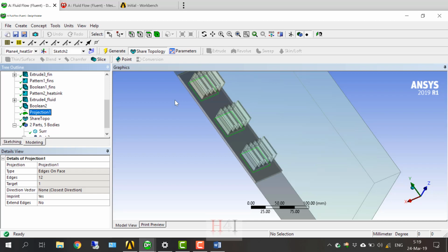You can mix these surfaces on this surface. I think it's possible, but projection is easier, I think. But I didn't try this option to draw a surface on the surface. What I want to know is if I should make a projection to make a link between this surface and the surface of the heatsink, or if I find it as a surface between four edges and define inside it the value of heat flux, it will work.